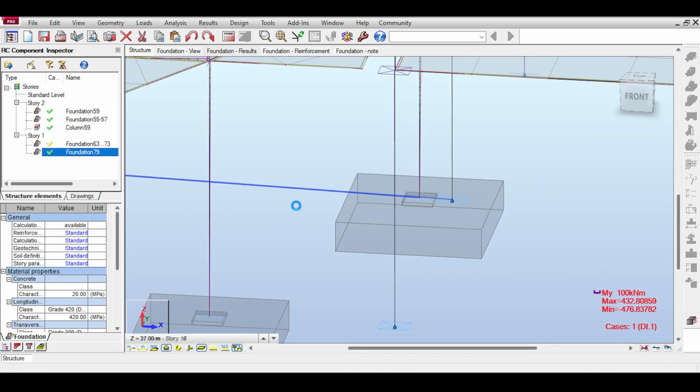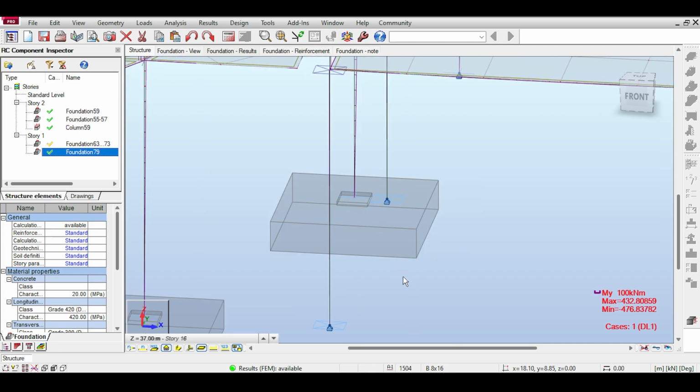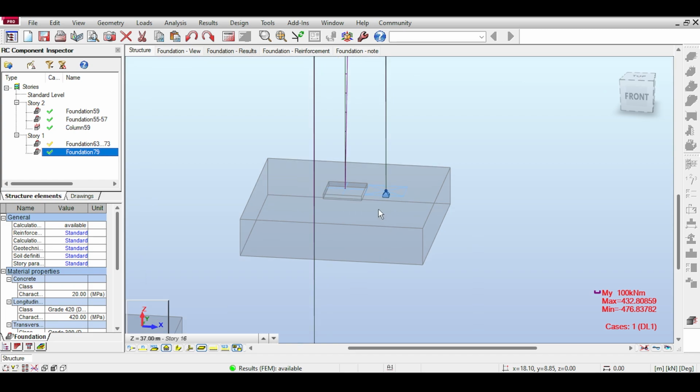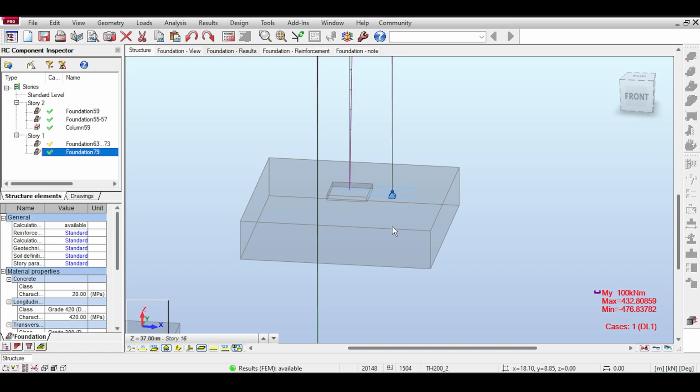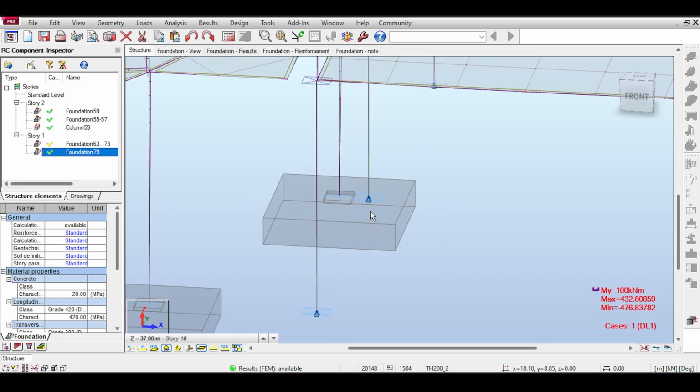Now, there are some geotechnical issues here. You should have the foundations spaced. If you don't have the foundations spaced, then the stress from the first foundation is going to overlap with the stress of the second foundation. We studied this in Braja M. Das's book. The stress cone is distributing in the soil in a 2-to-1 fashion. So in this place, you would have stresses from both columns. Now, how do you do this? You would have to design your foundations first and then check the overlapping stress.